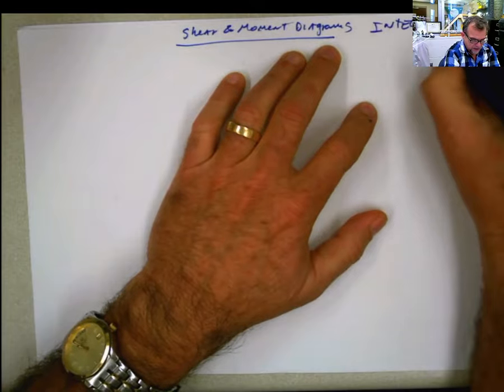Now the next thing that you do is what? You go to the point C, because remember, point, span, point. Now at point C, is there any concentrated shear at C? And the answer is, check it. 5, 4, 3, 2, 1. Nope, there's not any concentrated shear there. Because there's not any concentrated shear here, we just continue and this value doesn't change. If I have a concentrated shear, remember that value should jump, but there is nothing else.